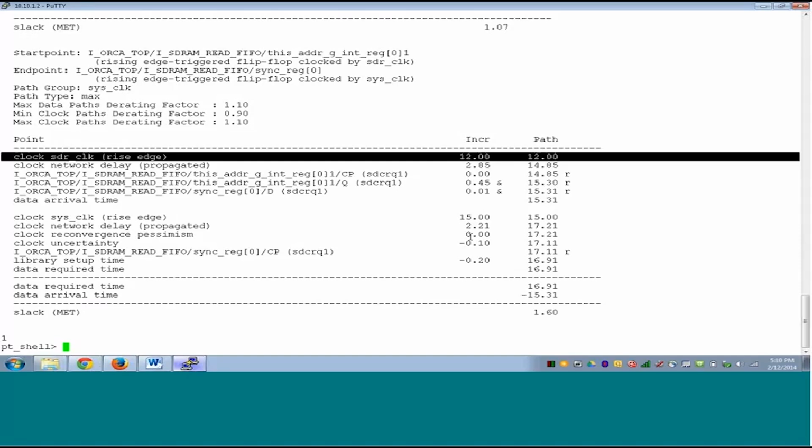So as an assignment, draw the waveform on paper for both these clocks. Assume one clock to be launched, the other clock to be captured. Do it for both cases. Fix the clocks, then make sure that you understand what the launch edges and capture edges are for both setup and hold.